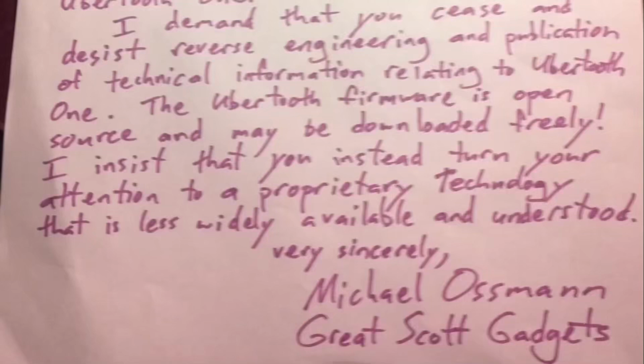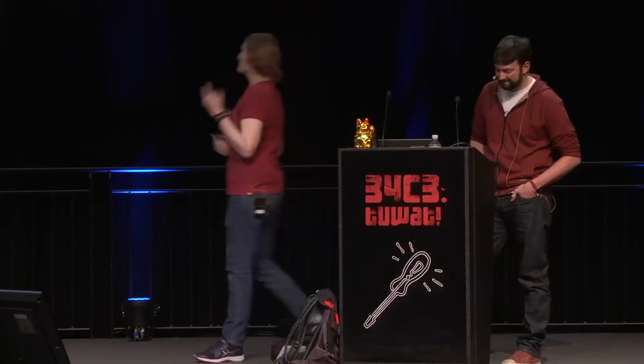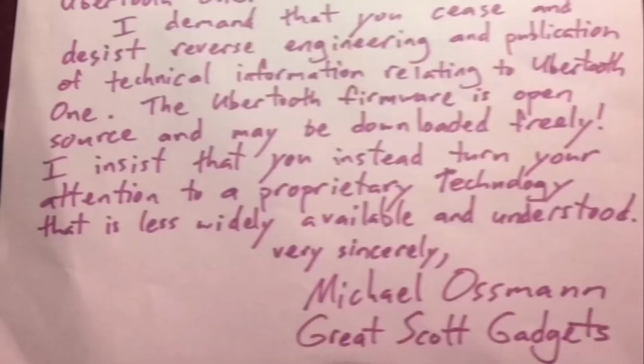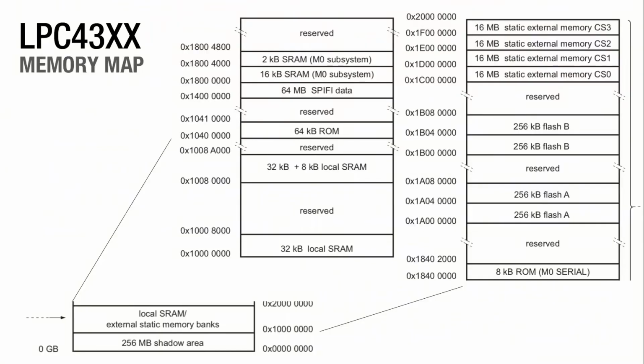Right. So because one, we already have the source code to this, and it's on GitHub, that doesn't make it a particularly interesting reverse engineering target. And two, because we're terribly afraid of litigation, instead of attacking the GreatFET software running on the application processor, we decided to attack the bootloader that is sitting in ROM on the LPC 4300 series microcontrollers. The LPC 4300 series have a USB DFU bootloader and also some other USB functionality, which is sat in ROM.